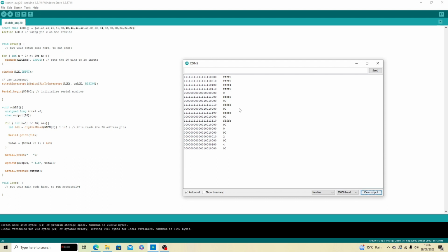The problem is it's going to be really difficult to try to write code in this small section of FFFF0 through to FFFFF. And if we look at that datasheet, it says this small region should be used to code a jump instruction to another part of memory where we can write our code. So the next step will be to code a jump statement at the FFFF0 location, rather than the hard-coded no-op, which I've done through the resistors.